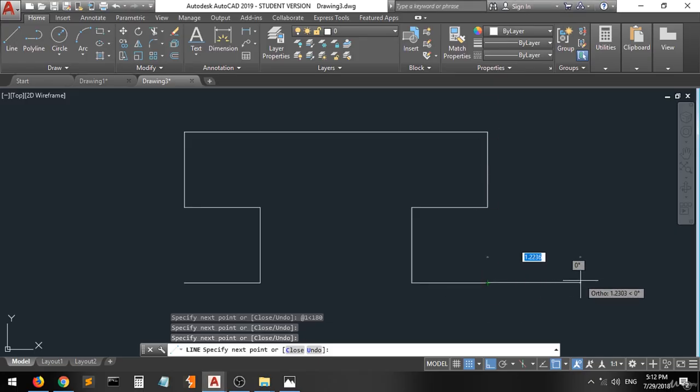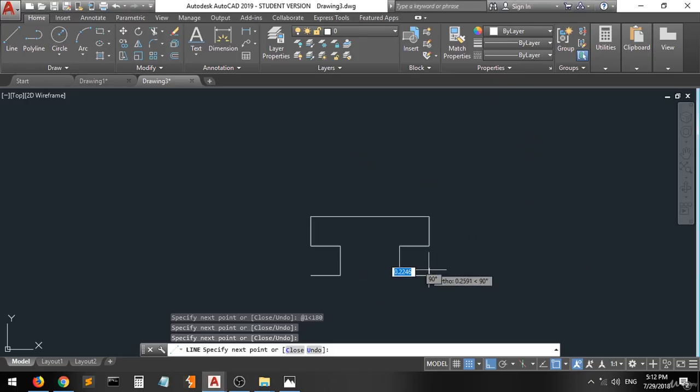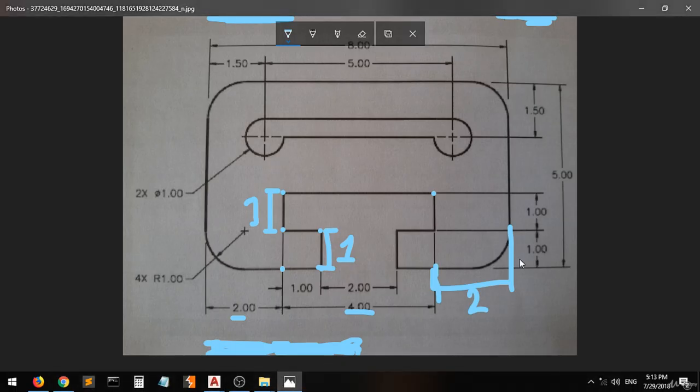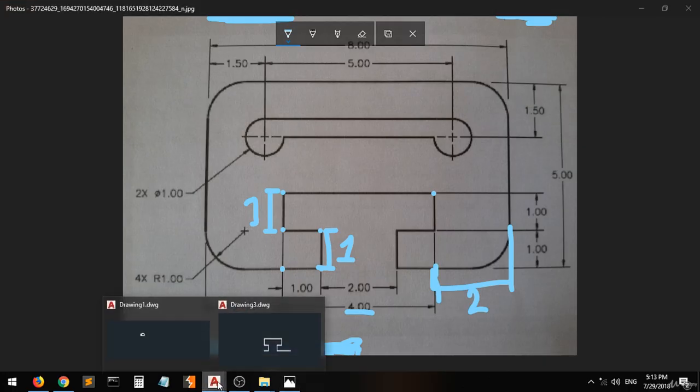So we'll move. Zoom back a little bit. We'll do 2 in the direction of 0. Excellent. Now, going back to the drawing, we will move this whole distance, which is 5. As we said, we will create it with pointed corners, then we'll create the fillet shape, okay? Don't forget this. We'll create it as a simple rectangle, then we'll do the fillet shapes, okay?